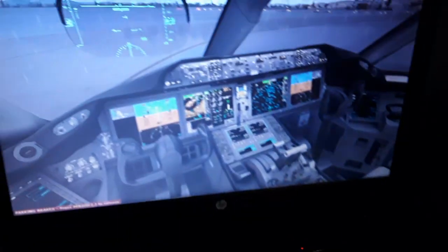We have also the navigation aids, the navaids like the ADFs and VORs, waypoints, VOR stations. So we have the waypoints, which are horizontal and vertical navigation features. The aircraft is going to have to traverse or fly through some waypoints as we're flying. So you will see how we're going to achieve that also. I'm going to use the flight management computer to input the waypoints we're going to use for flying this aircraft in the LNAV and VNAV function, the lateral navigation and vertical navigation modes, which are interconnected with the autopilot flight director system and also the autothrottle for automatic navigation.